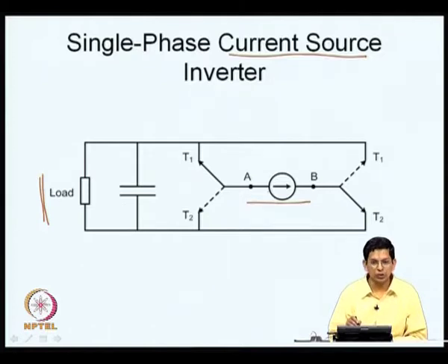The current source, again the current flowing through the current source should always be provided with a path, it can never be opened, a current source can never be opened. So, the current pertaining to it should always have a path to flow through.